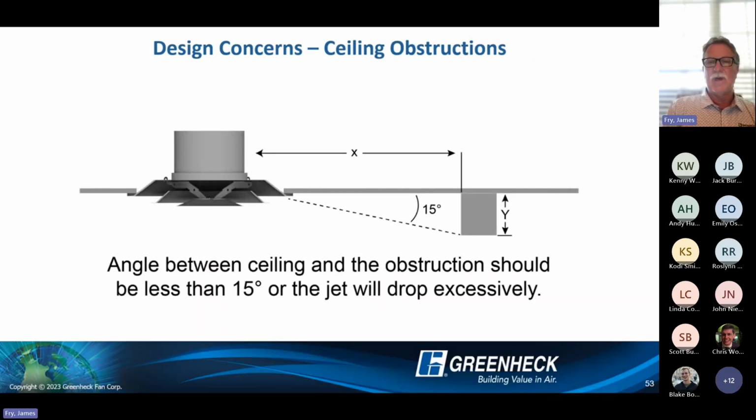Have to know what's in the way of that airstream. If there's beams or soffits in the way, we need to make those considerations. All of our products are adjustable from 1 to 4-way blow. Even in this product here, which is a 5700, we could put directional baffles in one side of it to not let that air go across there and hit that beam.